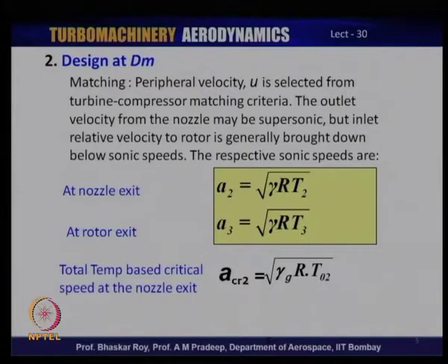of the blades, unlike in compressors, where they reach supersonic or transonic near the entry of the blade rows of rotor and stator. So, in the case of turbines, it is the exit flow conditions which are more important and quite often used for normalizing purposes.